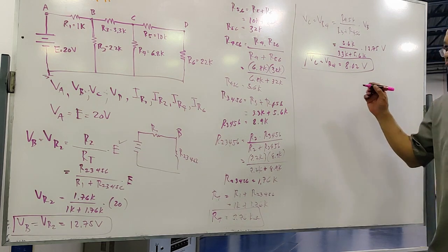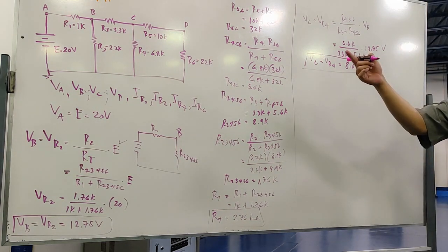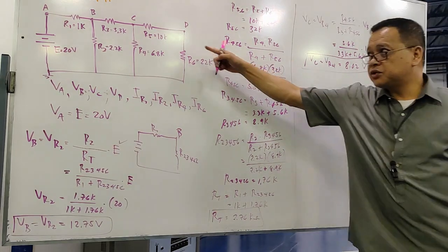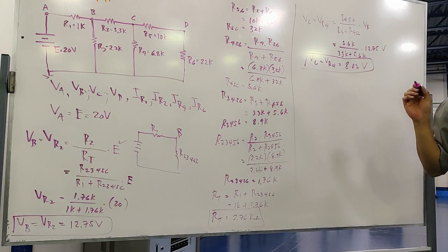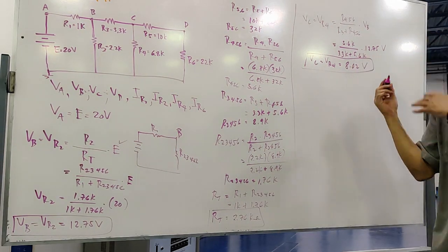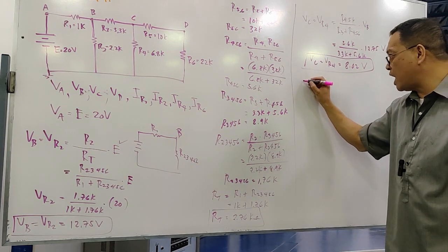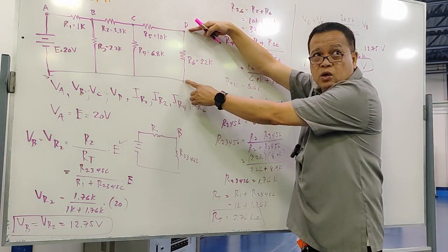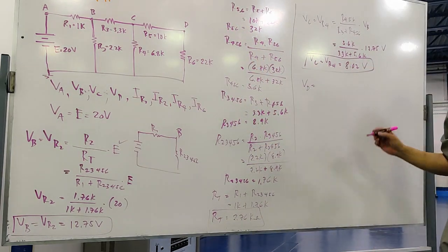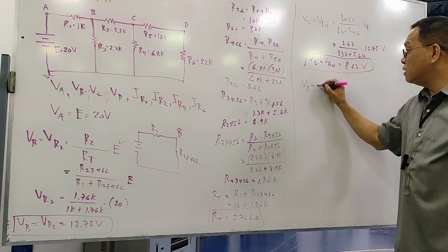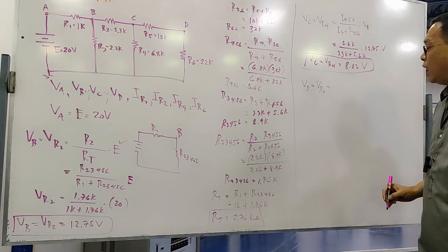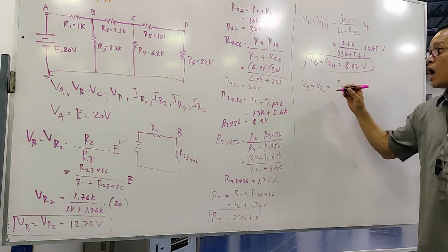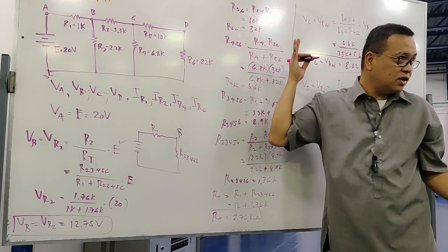Good. Next. The last one is so simple because it only consists of these three resistors. So it's much easier now, right? Same thing, just moving, like a pattern, right? So BD now is actually equal to what? BD here is actually the voltage across R6, correct? And that would be R6, because there's no other resistors here. R6 alone.